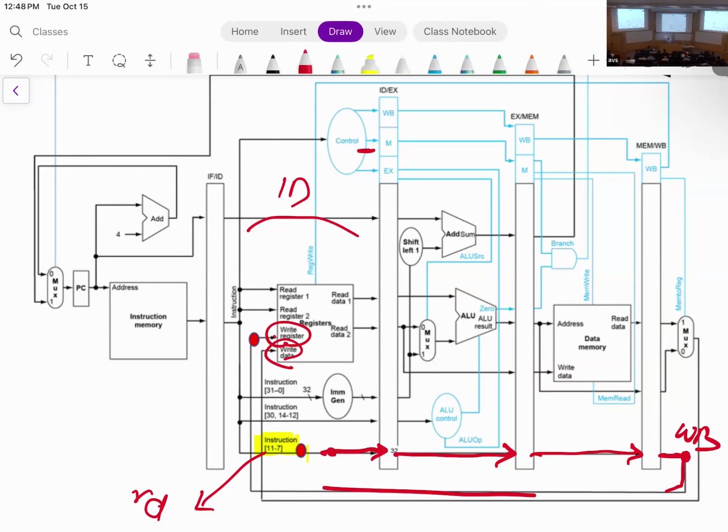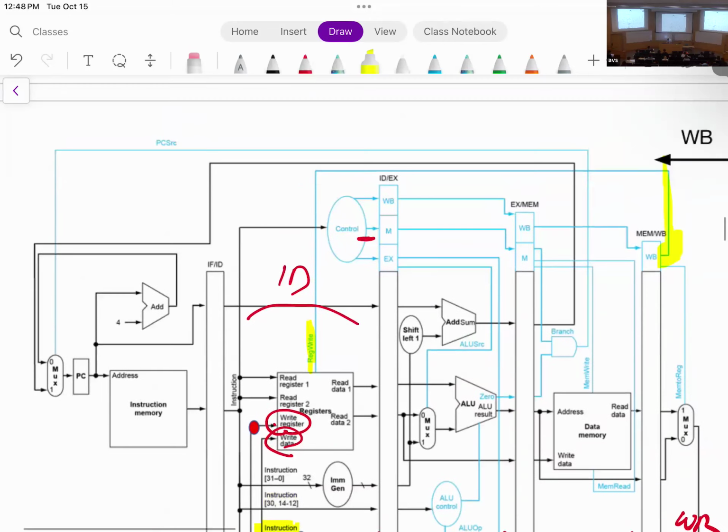I'm reading this value from the write back stage. And again, as you can see, the register write is also coming all the way from here. You can follow this; this is the signal that's being written. So I created things in the decode stage, and 3 cycles later, I'm going to use it back. I'm doing this by just wiring this from the right registers.